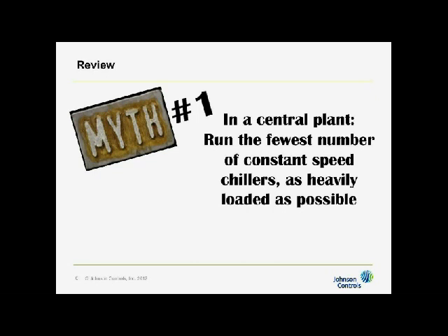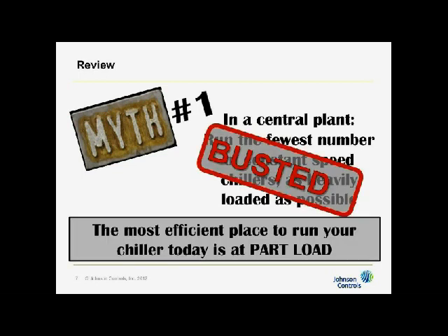If that's done, then it is cheaper to run 2 chillers than 1, whether they're constant or variable speed. Again, the same rules apply, that you need to be at lower head when you do that. So that myth was busted last time. The most efficient place to run chillers today is at part load.